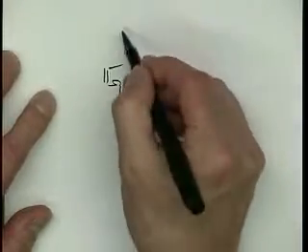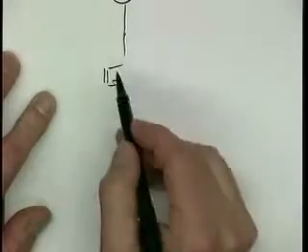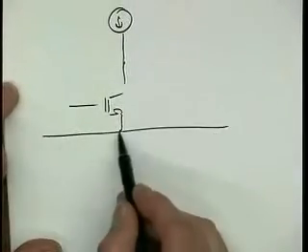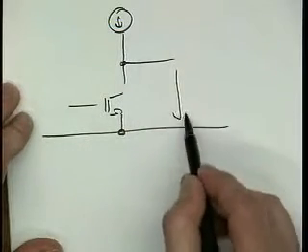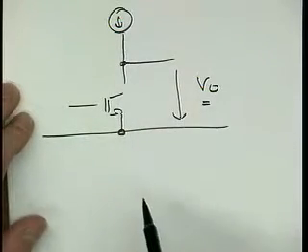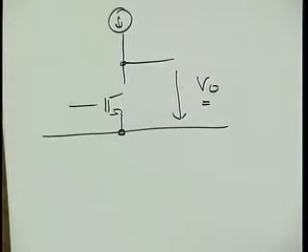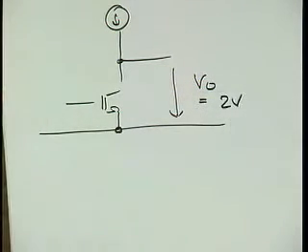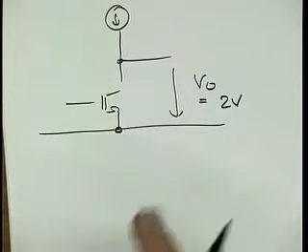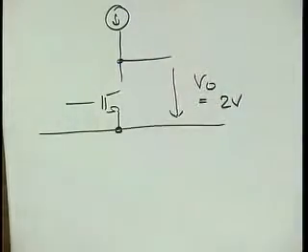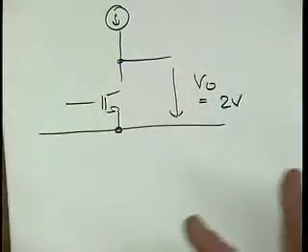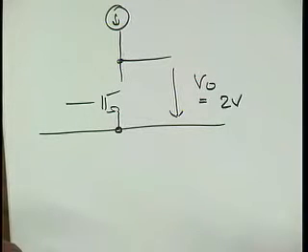So we build an amplifier, and let's for a moment even be generous and assume that somebody gave us ideal current sources. It would be nice, right? And this is therefore the output, the out. And in order to have that peak gain, we have to define that the output is 2 volts. Do you think you will sell many of these amplifiers? Not very useful. First of all, most of the time, VDS actually varies all over the place. Here it's the output of the circuit. Even in a cascode, it may vary a little bit, and more importantly, it's certainly not going to be 2 volts all the time, right? Because that would be 2/3 of our supply voltage.